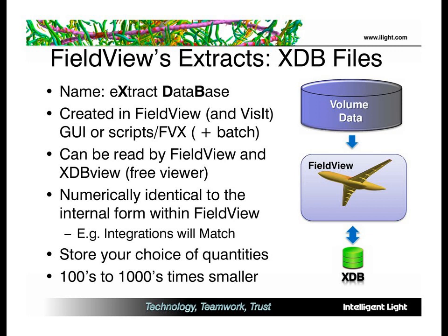There's no lossy compression. There's nothing like that. It's simply the fact that the surfaces that make up the things of interest, like an aircraft fuselage or a cutting plane, don't have to carry all the three-dimensional topology of the solver. And, as you all know, many of the cells in the CFD calculation are needed because of the fidelity of the calculation that you're doing. But in the end, if you're interested in forces and moments or mixing fractions, that can usually be derived by a much smaller subset of the number of cells in the data set.